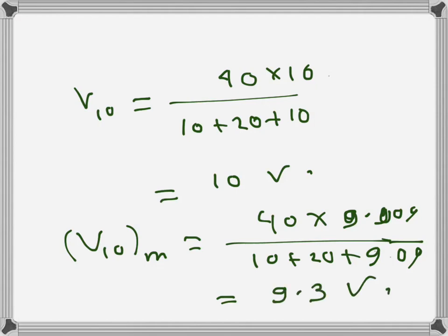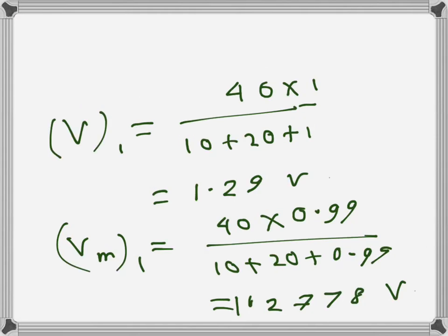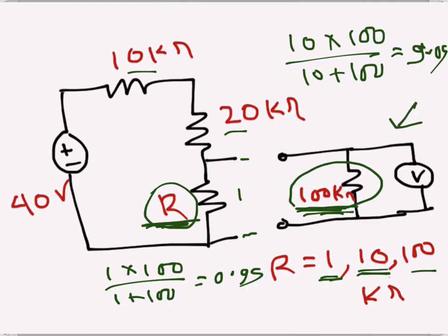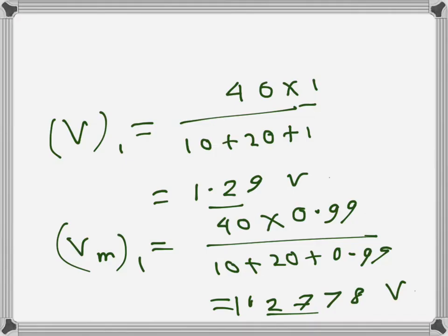Here the difference is a bit more than the difference there was before, the percentage difference, and that happened because the resistance across which the voltage is measured is now a bit higher. It is a bit closer to the voltmeter's resistance, though it's still just 1/10 of that resistance, but previously it was 1/100th. So the voltmeter resistance was almost negligible, but this time not quite.